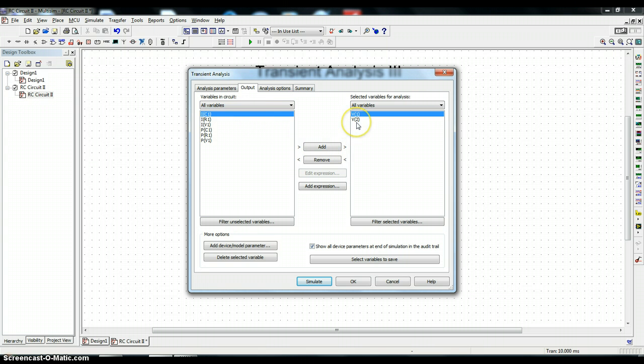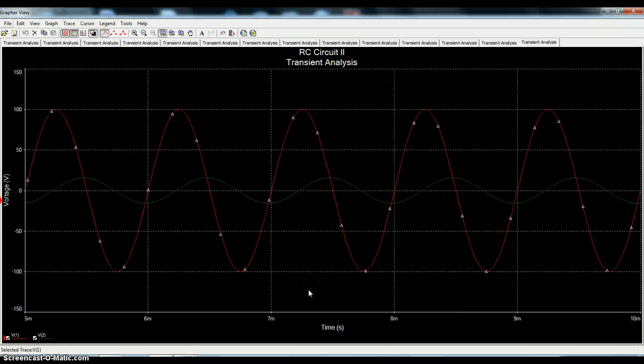Well, in this case, it's already been set. I could start from scratch and set them all over again, but I don't think that's necessary. The first case here is I'm going to show V1 and V2. Now, V1 is the input voltage and V2 is the output voltage. Also, I'm going to simulate the time step that has been set for a time duration from 5 milliseconds to 10 milliseconds. So let's see how we obtain the results in this particular case.